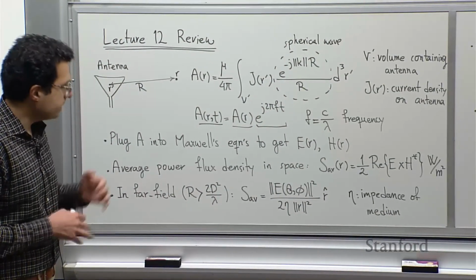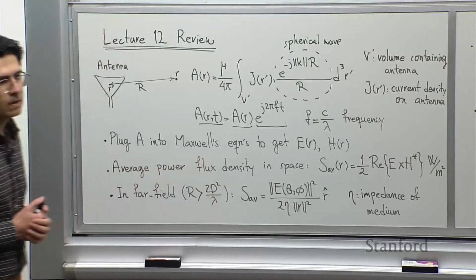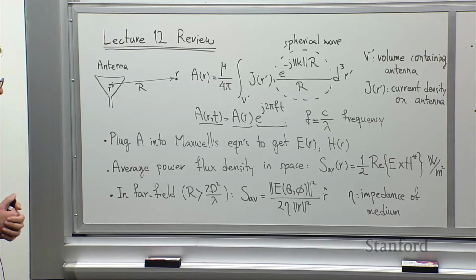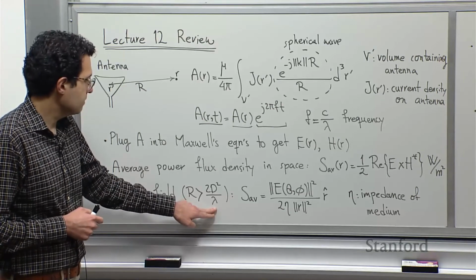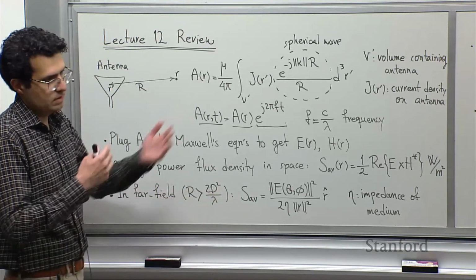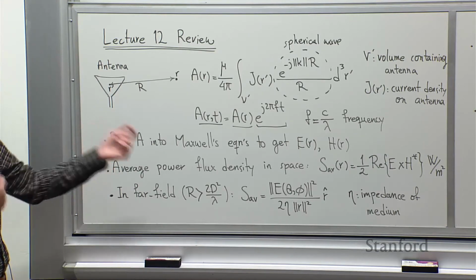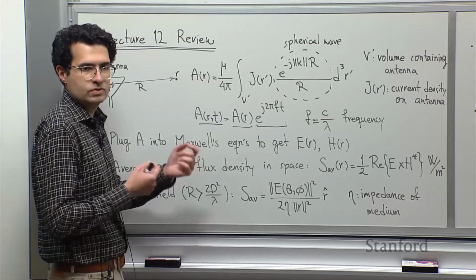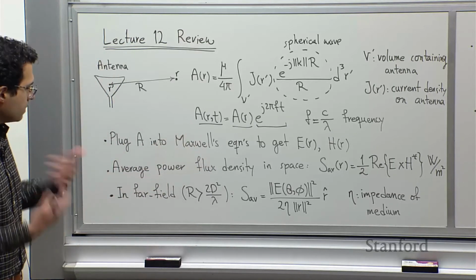Okay. And again, if we plug in some typical numbers for use cases in autonomy, like a lambda of a few millimeters for, say, a 77 gigahertz radar, and a D that is also a few millimeters, it turns out that it's far field, but physically you don't need to be that far. Usually a few inches away is already considered far field. Why is far field important?